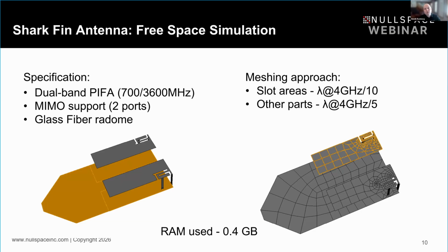So compared to, for example, an adaptive process that is used in CST or HFSS, where you just hit play, it goes through these different iterations where it improves the mesh, and hopefully before you are out of your adaptive max passes, you will have a good enough mesh that will actually give an accurate result. But here in Nullspace, we are skipping those steps by controlling the mesh ourselves from the beginning.